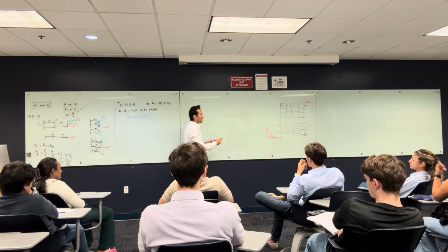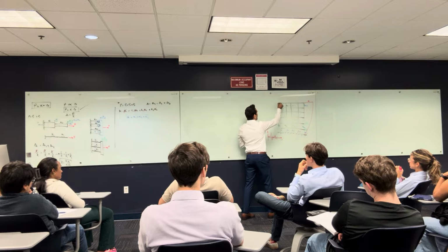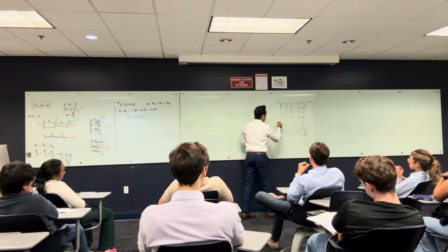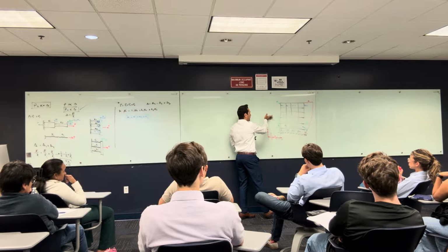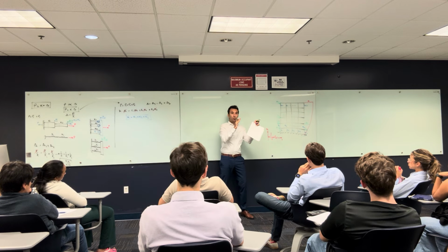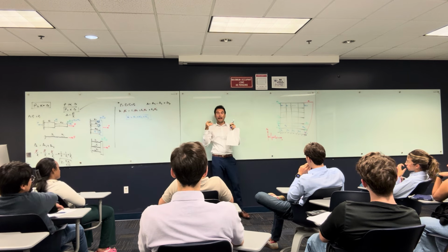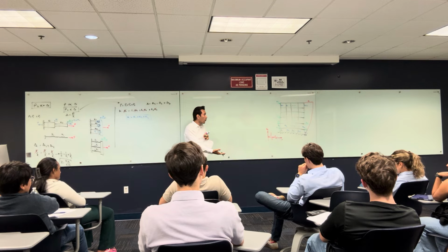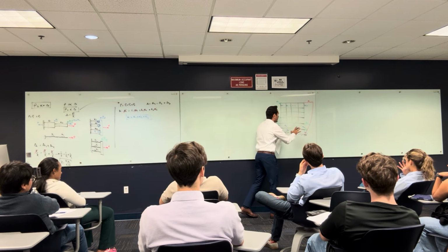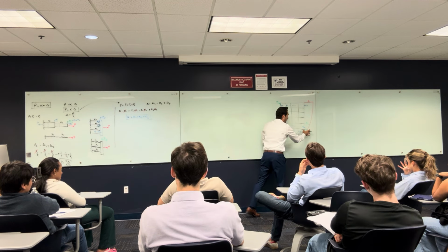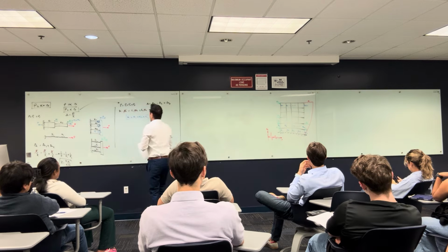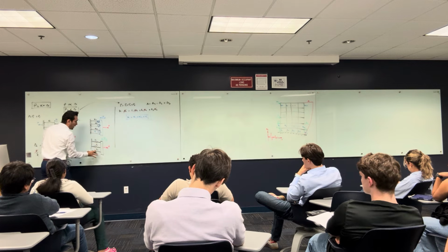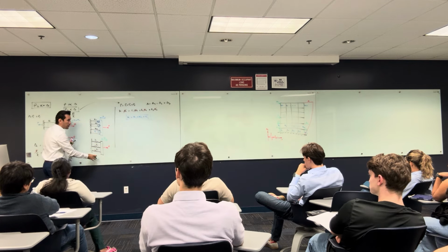Once the seismic load happens, this system is going to have B1, B2, B3, up to Bn. Why? Because the more you go up, the more the mass absorbs more forces, or has inertia to take more forces, potential forces that are going to happen on this slab. So you are going to have delta one. All the columns of a slab under the same force V1 are going to have the same delta. So that's a parallel system, like this system.